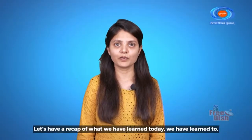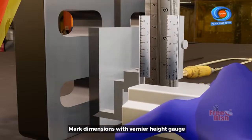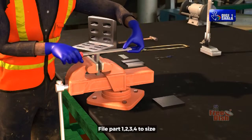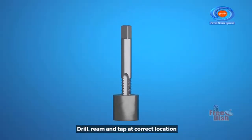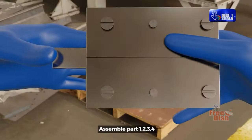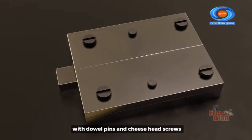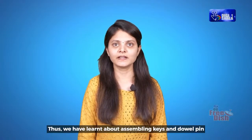Let's have a recap of what we have learned today. We have learned to mark dimensions with vernier height gauge, file part 1, 2, 3, 4 to size, drill, ream and tap at correct location, counterbore to the required depth, assemble part 1, 2, 3, 4 with dowel pins and cheesehead screws. Thus, we have learnt about assembling keys and dowel pins.